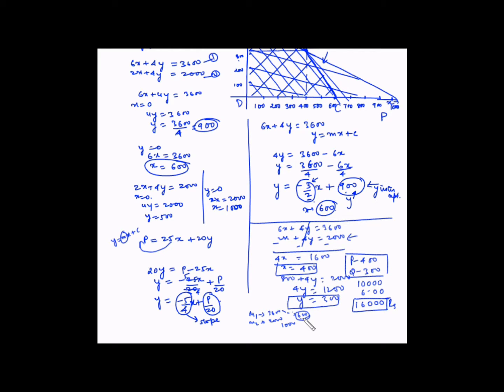So what that did is that machine M2 remained underutilized. 600 units at 2 hours per unit is 1200 hours on M2. So 800 hours on M2 were underutilized or not utilized.